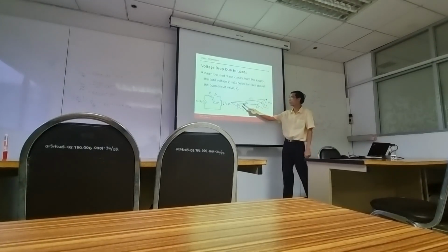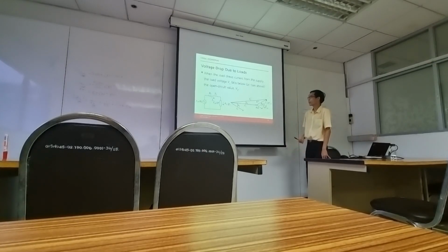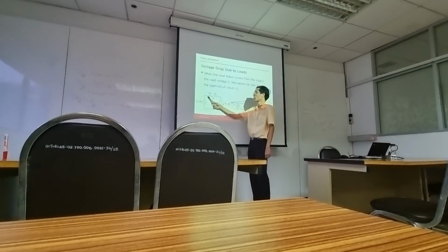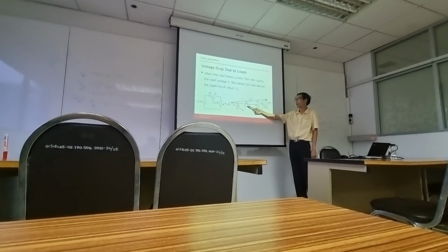And then you can find the source voltage Vs, which is this one. Because there is a voltage drop across the resistance and inductance, the load voltage and the source voltage are not the same. The magnitudes are not the same, and the angles are not the same either.